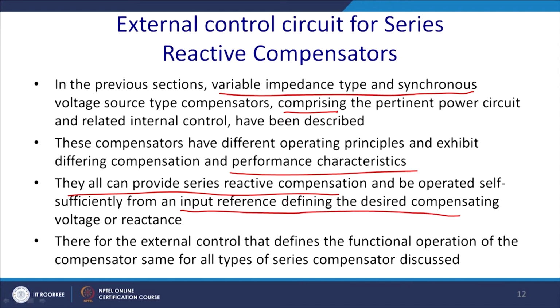Therefore, the external control that defines the functional operations of the compensator is the same for all types of series compensator discussed. Ultimately it will inject some amount of VAR to the system. Whether it is the impedance method or the voltage method, externally they look equal.